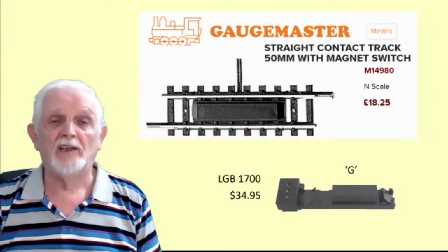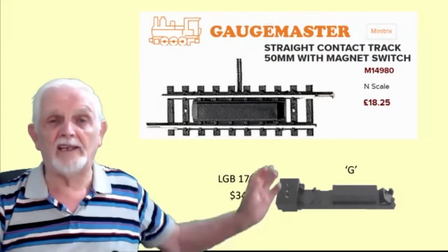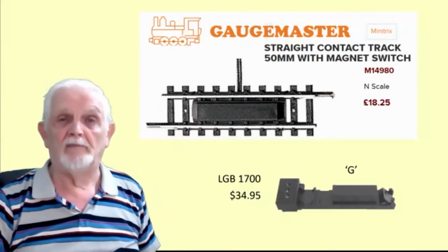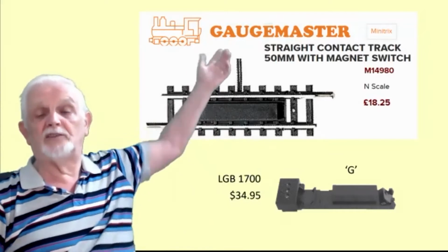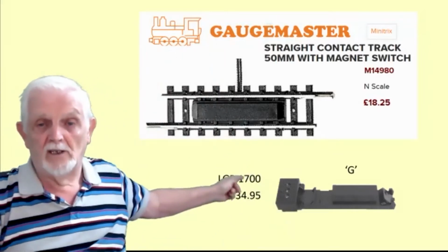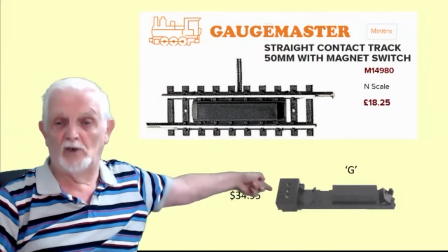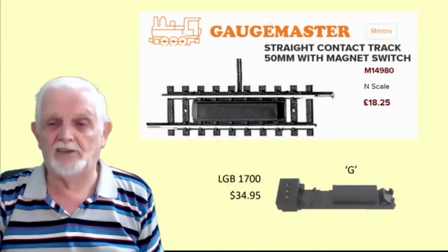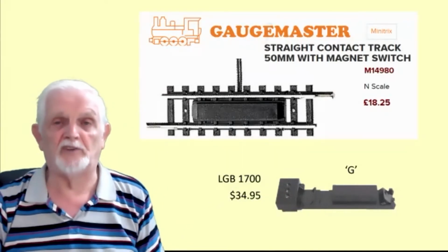And the idea is, if a train has got some kind of magnet, as it passes over, it'll make the reed switch operate, and a signal will come up these wires back to whatever you want to do with it. And down here you'll see again contacts coming out of the module. And at the very end, that's where the reed switch is, under the track, between sleepers.